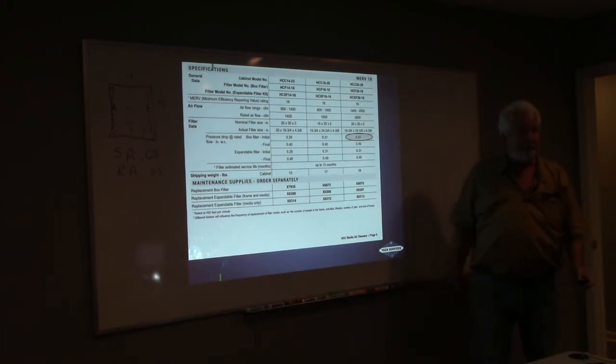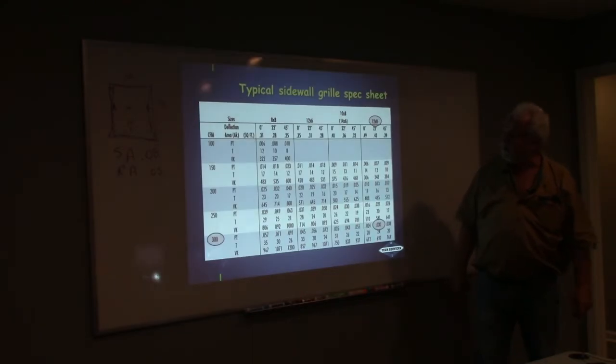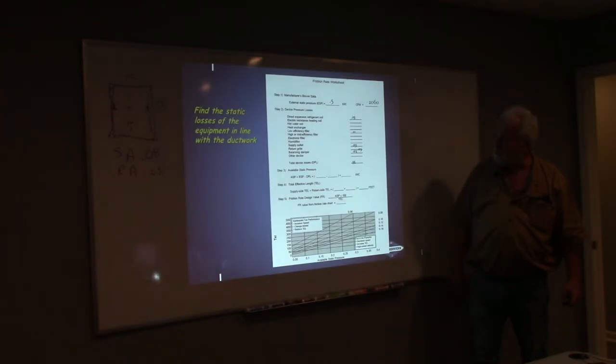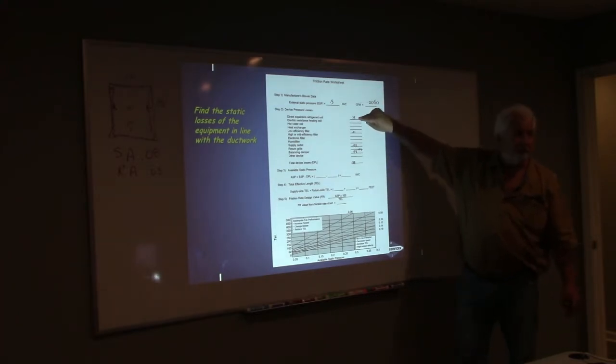So the type of filter we're throwing in there is going to make a big difference. Look, here's our typical wall grill. What did I say the typical wall grill would be? Somewhere between 0.2 and 0.3? Good. So let's go with a good 0.3 there. So you see where I got all these numbers, yes? So I'm filling back in here. The coil was that 0.15. Or if we were going to that 17-inch coil, it was 0.3 something. Is that right? Yeah. Good.